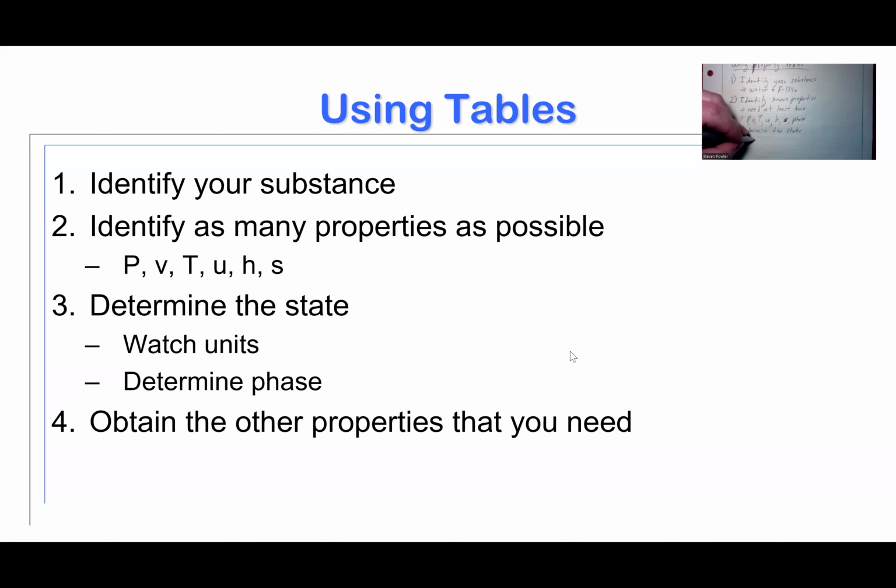There's this bullet here that says watch units, right? So make sure you use the appropriate unit set of tables. Don't just convert everything to metric. That's pretty lazy. I get that there's some advantage as far as units go, but units really aren't that hard once you figure them out. The biggest thing is once you convert to units, you might line up with nice round values in English units. You convert them to metric, you're no longer going to line up with nice round values, and you're going to be between rows in the tables, and it's going to be a lot more work for you than it's worth.